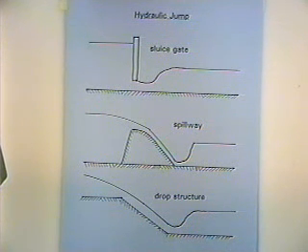And so the basic concept is this. This is the basic principle. To have a hydraulic jump, you've got to go from supercritical flow to subcritical flow. I'll not flip back in the notes, but on the diagram you notice when the specific energy is a minimum, we've got sort of a curved surface where there's a very significant change in depth for a relatively small change in energy. The water surface will jump up and down when you get near critical flow. And that's what's happening with a hydraulic jump. It's really jumping up very abruptly.